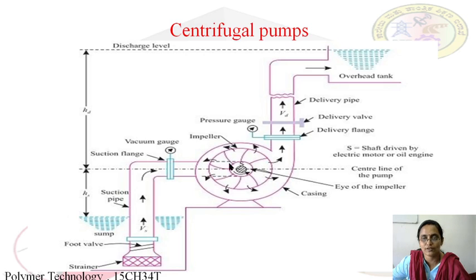The liquid also rotates with the impeller, and while leaving the impeller, kinetic energy will be imparted to the liquid. This kinetic energy, on leaving the vanes of the impeller, is converted into pressure energy, and this causes the fluid to rise through the pump.